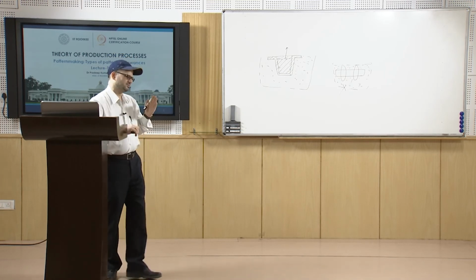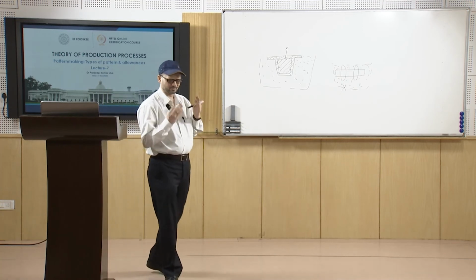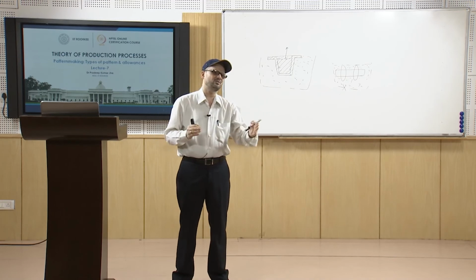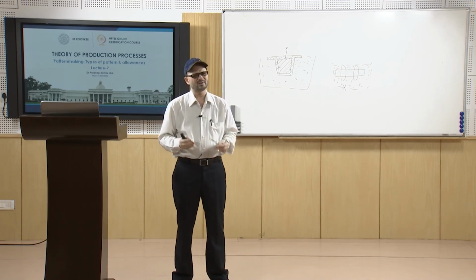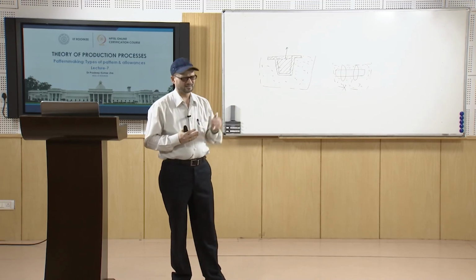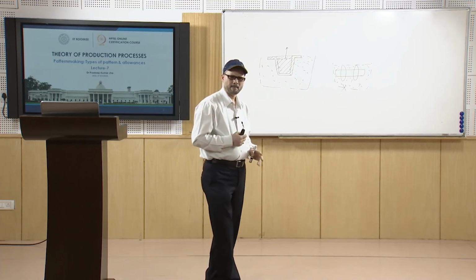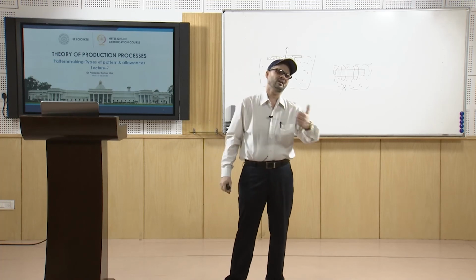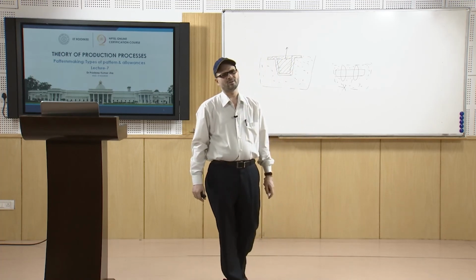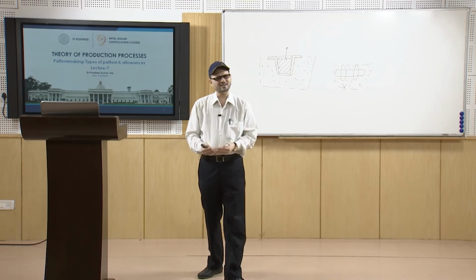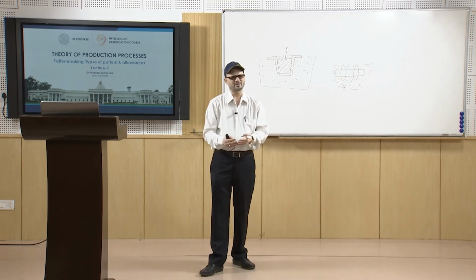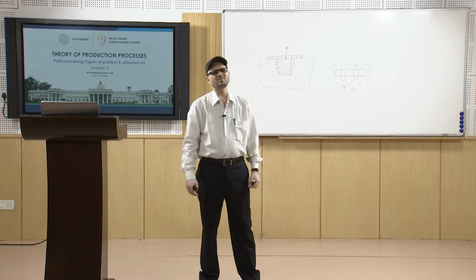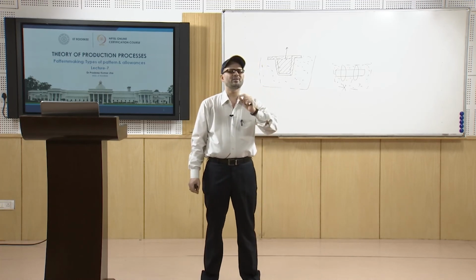The hot metal goes into the cavity and sometimes reacts a little with the sand. You have fusion of the sand, which sticks to the surface. Many times you will have a glassy appearance, maybe because of improper molding materials. You have certain surface reactions, and sand-metal reaction maybe in extreme cases. So, normally the surface will not be very smooth.